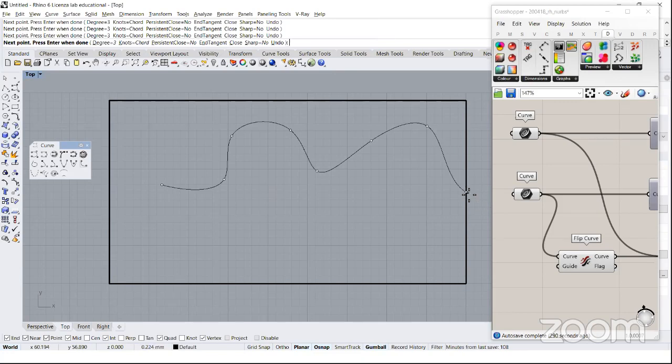If you do this, the only way that you can touch the border with an interpolate curve is to place one point on the border itself. So you need to place the point here. But the shape of the curve depends on where you place the next point. So you see that if I place it here, the previous segment keeps dancing around, and so the curve might go out from your boundary. Also, even by placing this next point here, I'm still affecting this segment here.